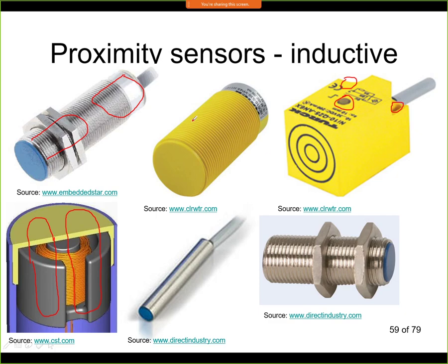It's also the case for those sensors that you see on the left, but in this case the LED would be on the back side, so it will be somewhere around here or somewhere around there. So we don't see this in the picture, but there is probably no sensor that does not have some LED, and the reason is that it's then very simple to see if the object is really detected or if it's not detected at all.